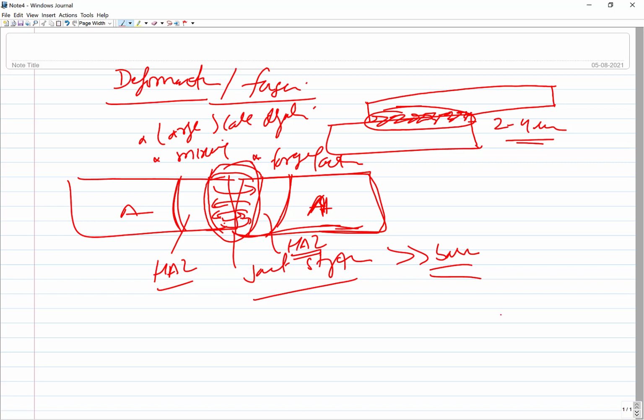Because the way the properties change in fusion or in deformation based approaches is, to a great extent, governed by the metal system, the metal strengthening mechanisms, and the way the particular metal being joined has been designed. So on that I will come a little later, maybe in today's lecture only. So the heat affected zone and the weld nugget or weld zone area, these are the two things.